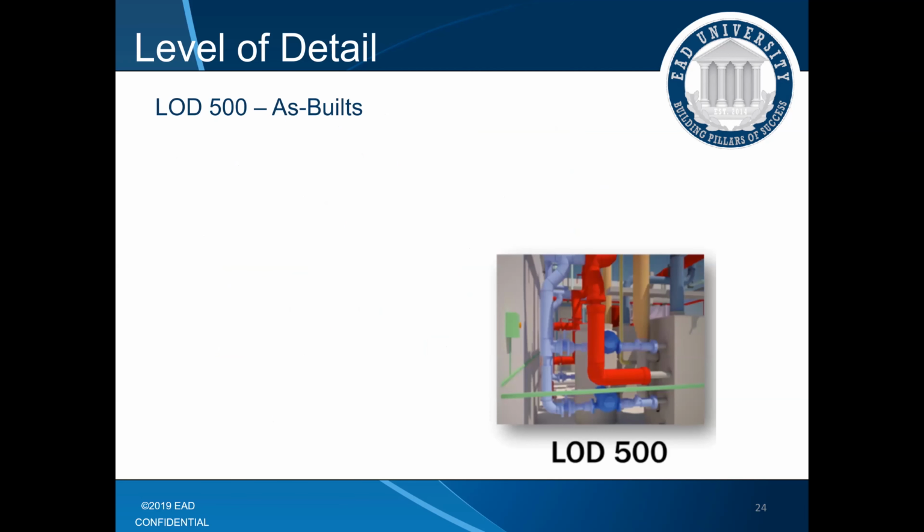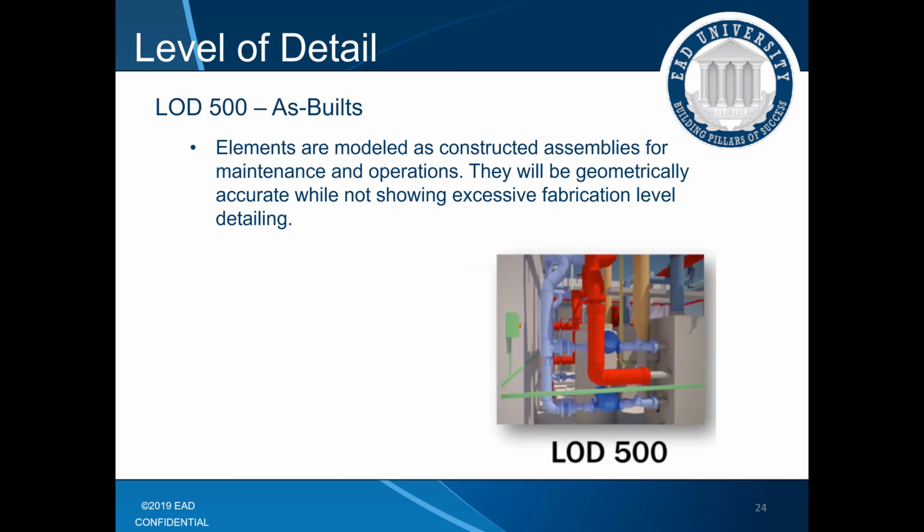LOD 500, this is the as-built stage. Elements are modeled as constructed, assemblies for maintenance and operations. They will be geometrically accurate, not showing excessive fabrication level of detailing.